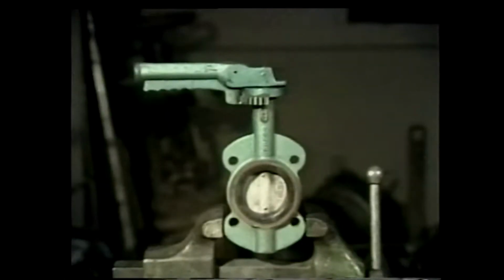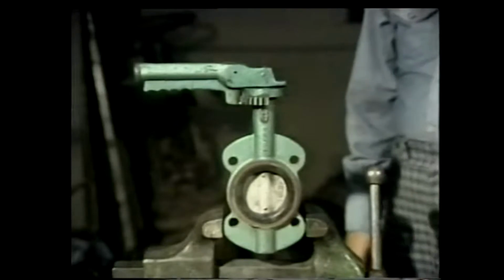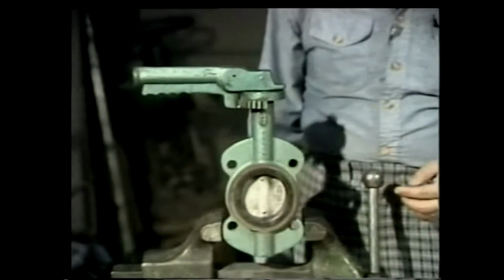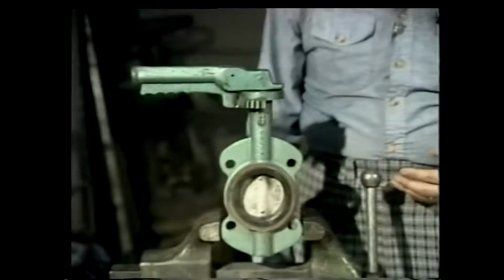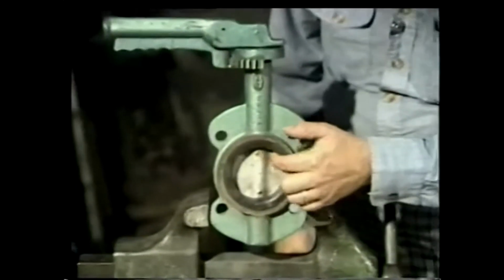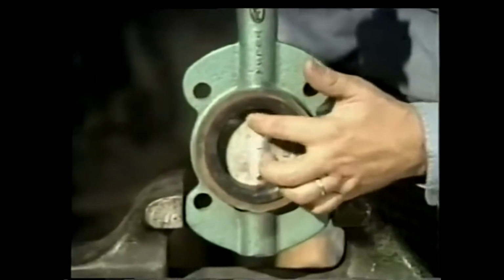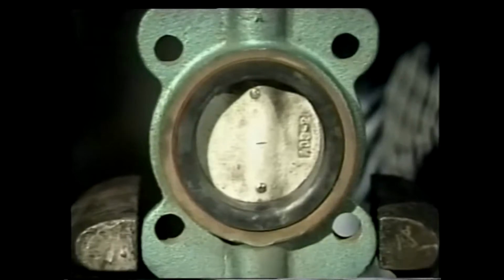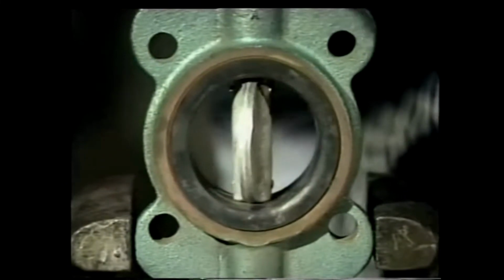This is a butterfly valve. Now, these valves are normally found in low pressure, low temperature systems. Butterfly valves are useful on large volume systems where space is limited. The disc on a butterfly valve is the same diameter as the piping it is attached to. When activated, the disc turns 90 degrees from the fully closed to the fully opened position. The position of the butterfly valve can easily be observed. When it's in line with the piping, it is open. When it is perpendicular or across the piping, the valve is closed.